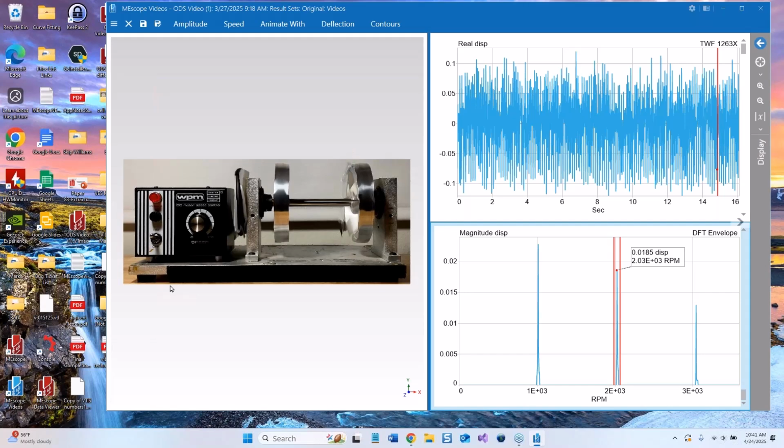The vibration changes, the base plate is not moving nearly as much, and that's at 2 times, and then here's the third order over here at 3. Now you can start to see the mode shapes of these. You see this mode shape here? The 2 sides of the rotor are moving differently, with what we normally look for in mode shapes, a deformation. It's a simple waveform like that.